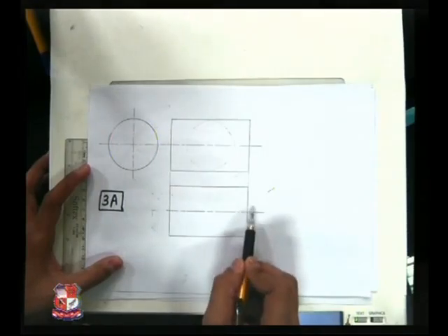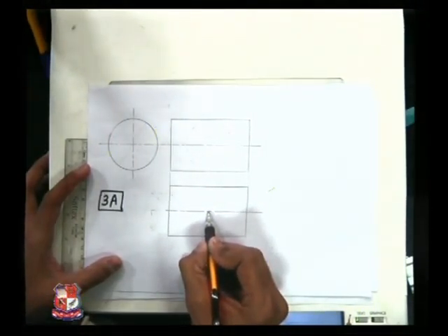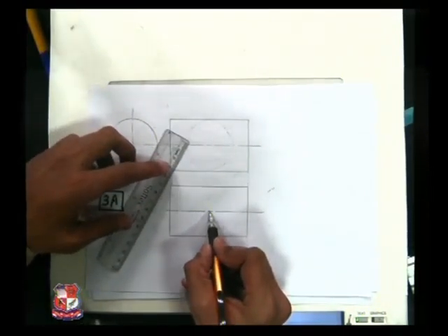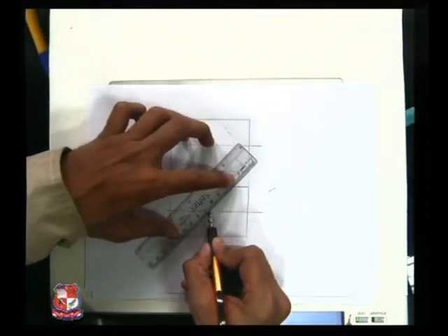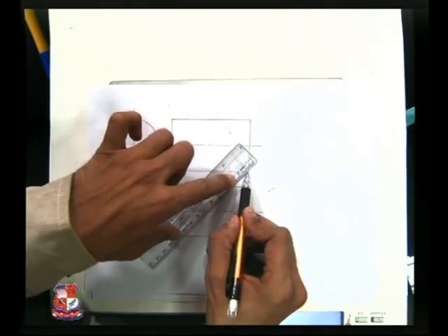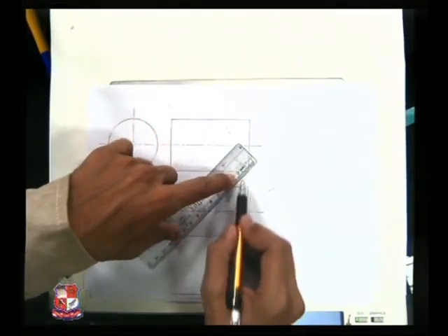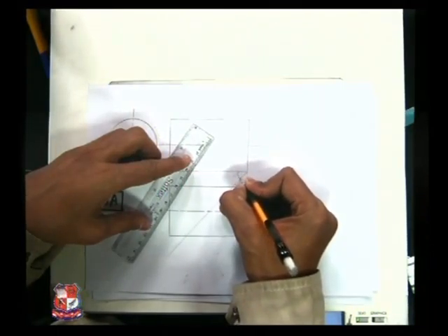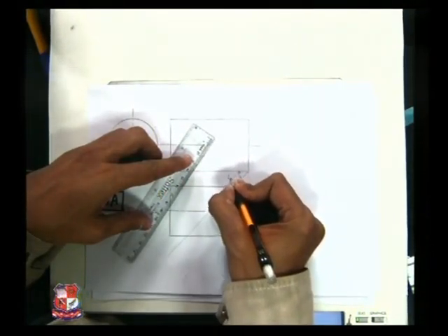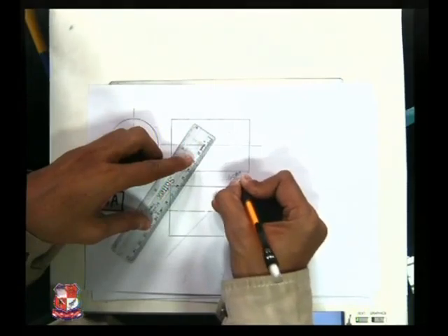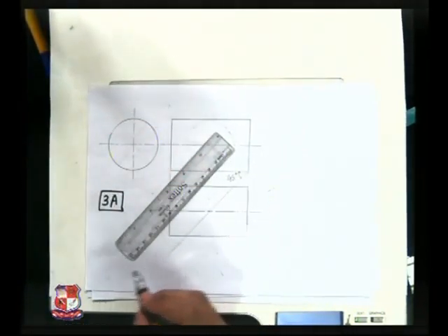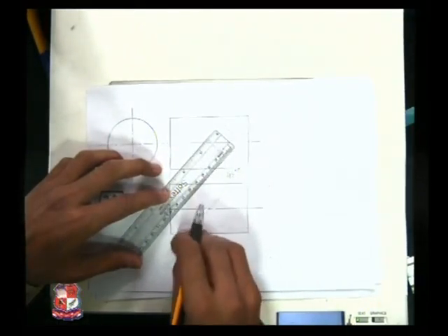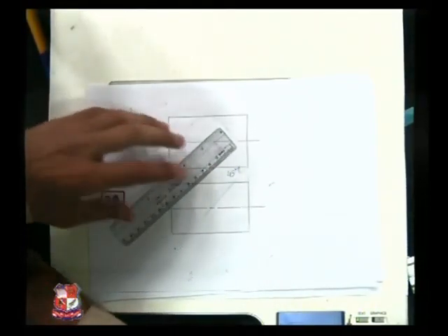Total width is 80 millimeter. So at a distance of 40 millimeter, mark a point, and we have to draw cutting plane in such a way that it will pass through this point and make an angle of 45 degree with XY line. So it should be drawn like this. This angle is 45 degree and this is the cutting plane,